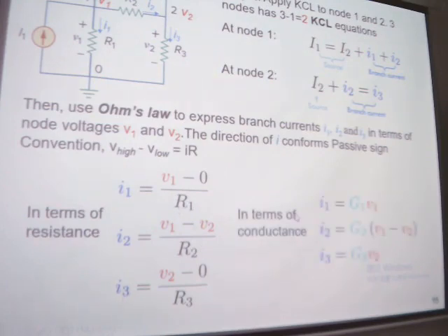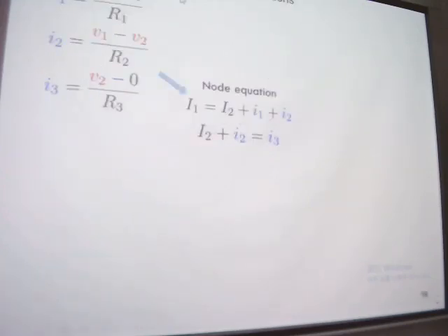And if we write this in terms of conductance, it's easier, right? It's the same actually, but it looks easier because G1 comes as a product, not divided. Yes, it's product, not divided. It looks like this, but actually it's the same, okay? Now if we are going to calculate I1 to I3, we need to put V1, V2 back to the equation, right? Back to the node equations.